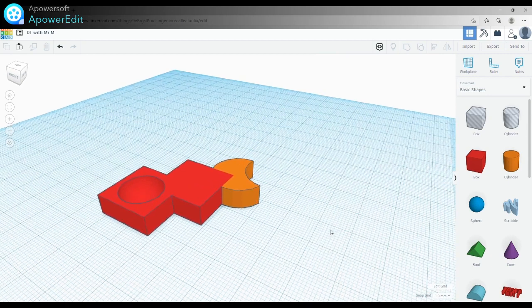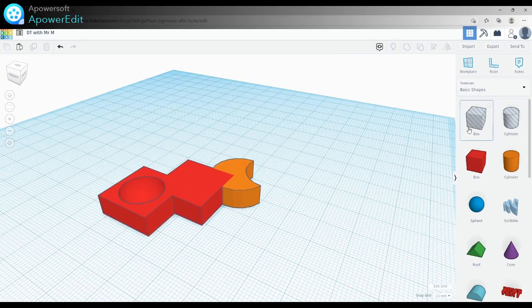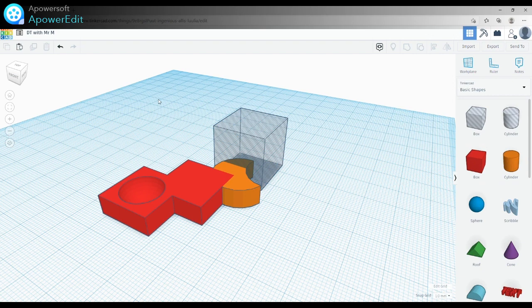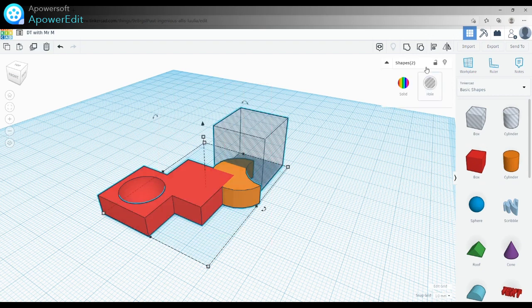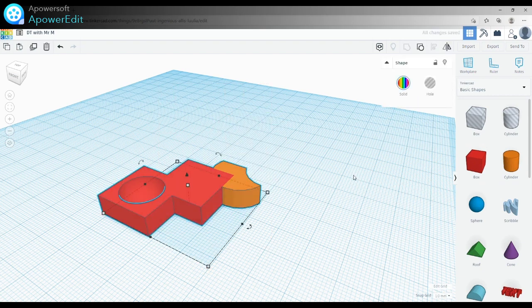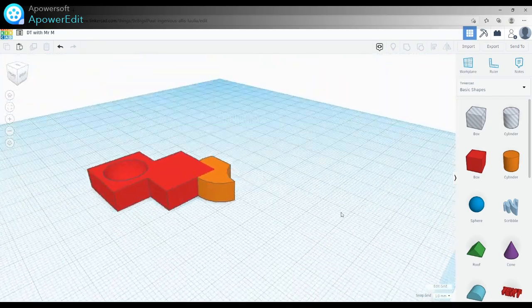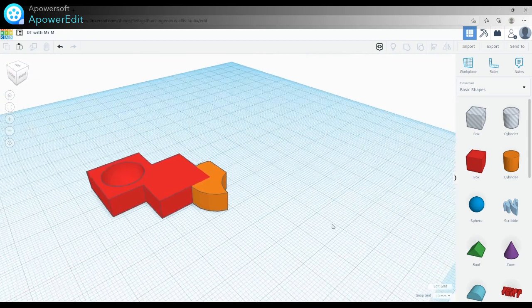There are some preset holes here. If I bring this in, I can use that, and it's preset as a hole, but it doesn't really matter because you could make any shape that you want into a hole and use that to cut out when you combine your shapes together. Okay, so by grouping we can remove material and do what we want to do.